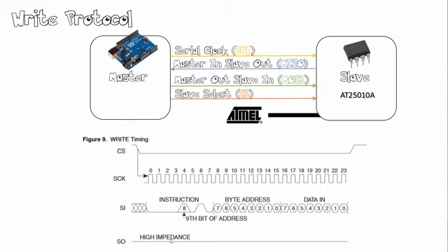Slave select or chip select is always low for an active slave. If you make the slave select of all slaves low, then you stand a chance of having conflicting data coming to your master. Now imagine all this data flooding your master from all these different slaves, and therefore we only select one slave at a time.